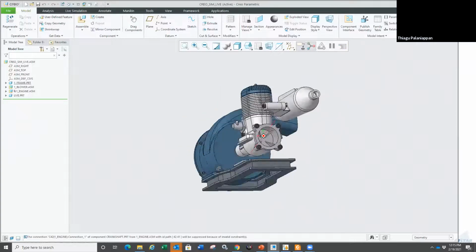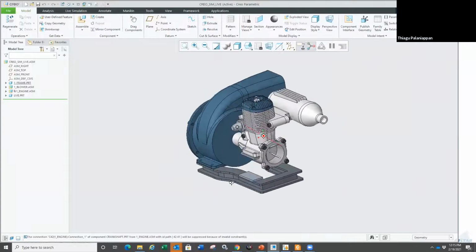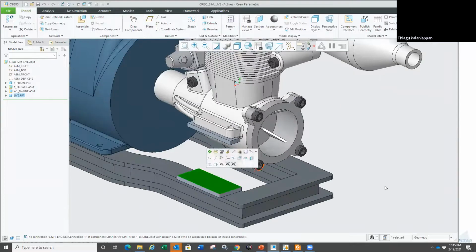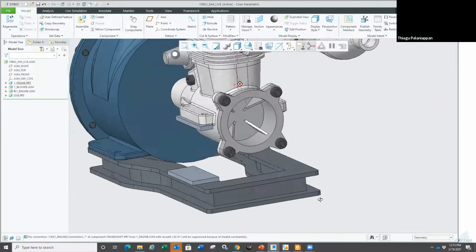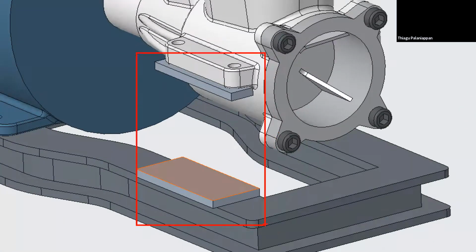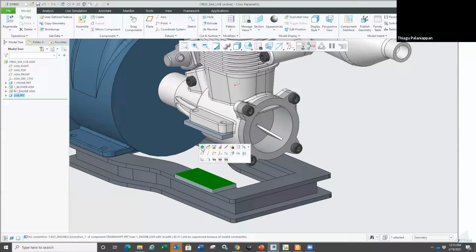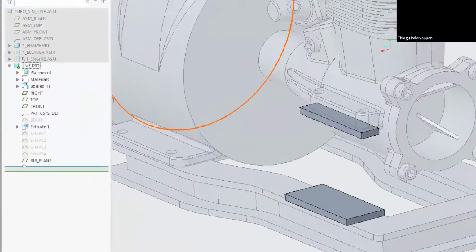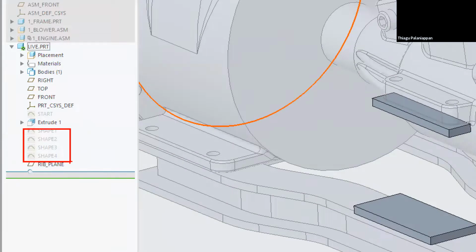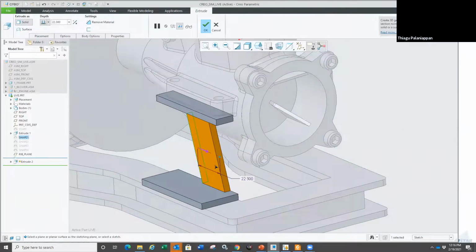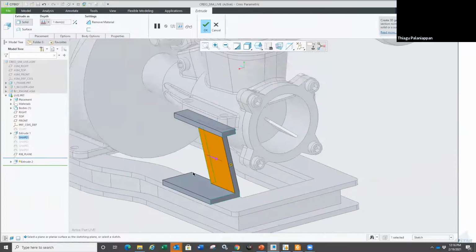this also helps for design exploration or in your concept design stage, right? There could be situations where, as you can see, I'm taking the role of a designer who doesn't have FEA experience, but I might want to create the support plate real quick and I'm going to activate that. I'm in my assembly mode and I'm in my regular day-to-day design activities here, right? I do have a few sketches already done, but I'm thinking I'm probably going to use this one here for my extrude, right? I'm going to just extrude that, shift selected, that snaps to it.